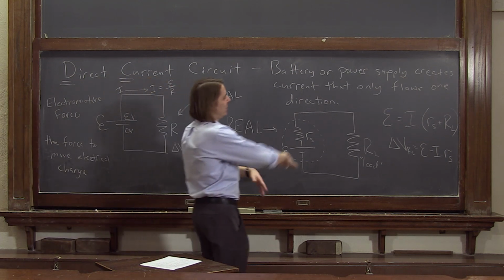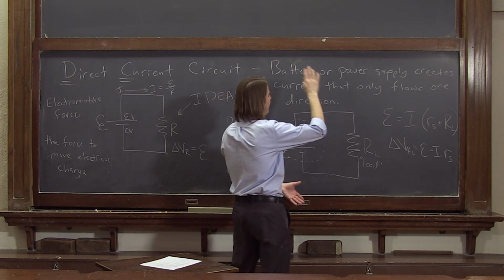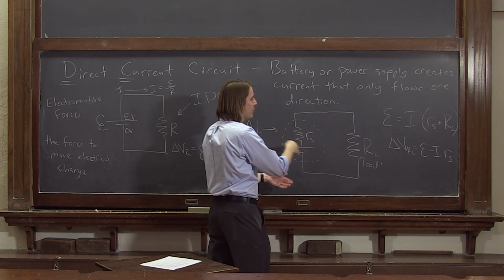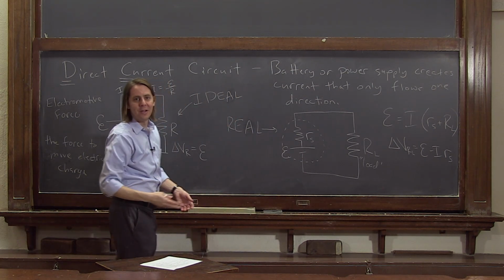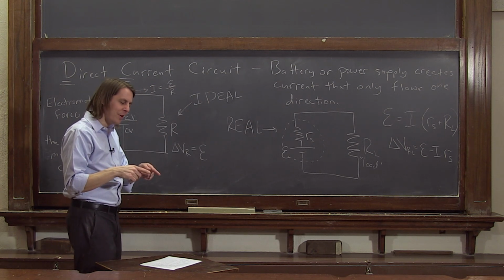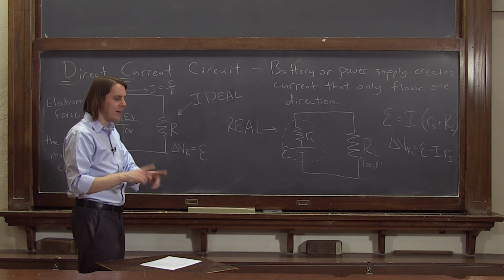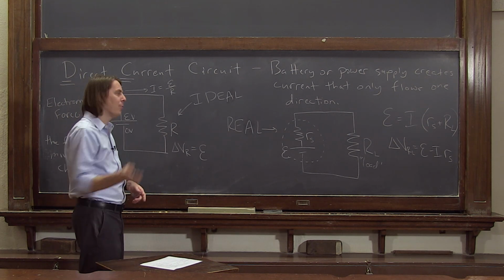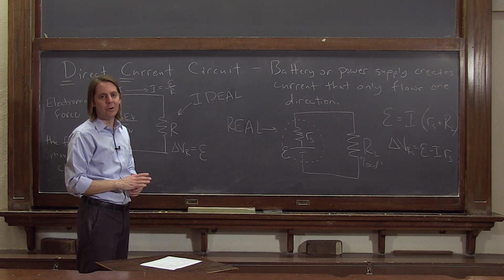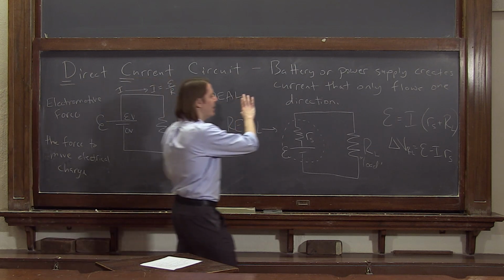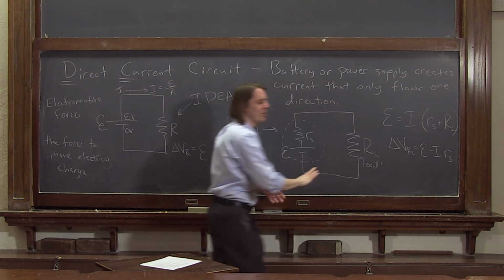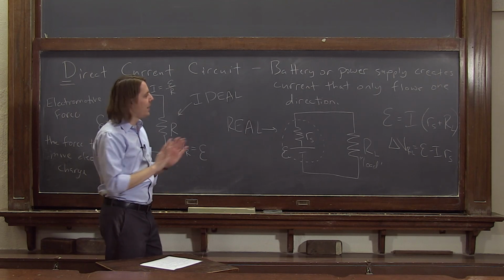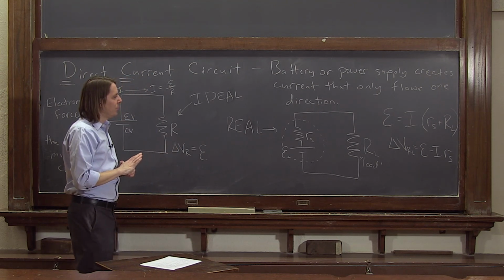When you just have a battery open to the air and R load is infinite, you get no current flow, and then you get the maximum. You do get the EMF. But when you're actually running a circuit, that EMF goes down. So if you have a battery or power supply and you measure its voltage with some really high impedance meter, you get a high voltage. When it's powering some circuit with a lot of current, it actually might be lower. So just one of the many examples of how real circuits are not the ideal things we're going to describe through most of the class. So anyway, now let's move on to some more complicated circuits.